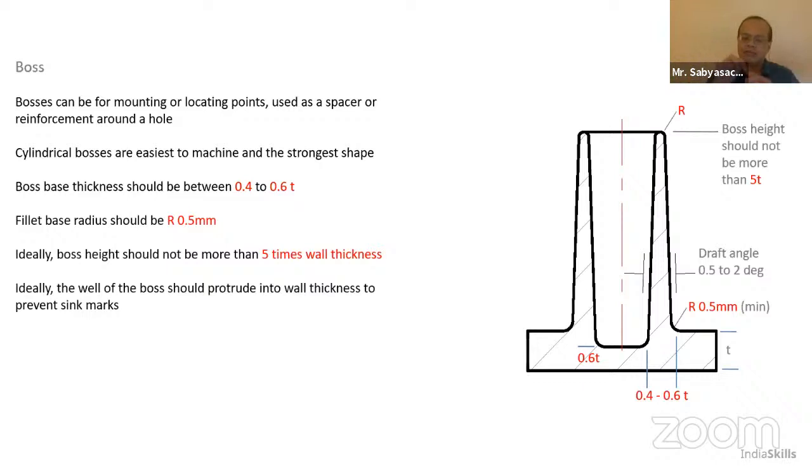Your PCB might have a hole which goes into the boss, so it will restrict the degrees of freedom of motion and not allow things to move around. You can anchor things to a boss. You can have a peg that goes into a boss. These are the kind of things that allow for placement.